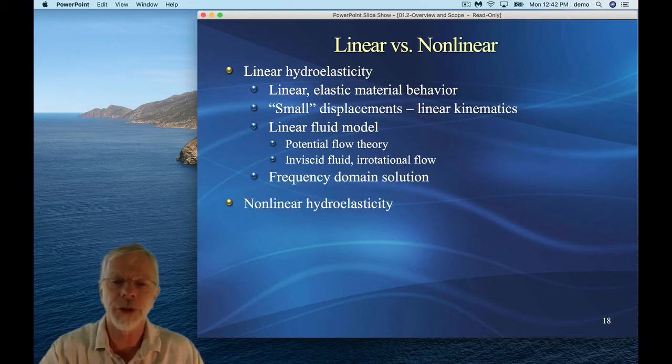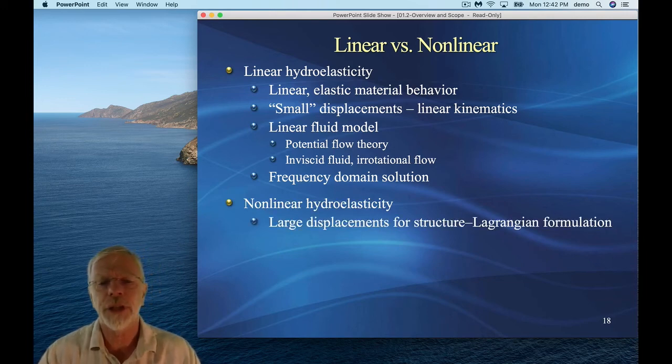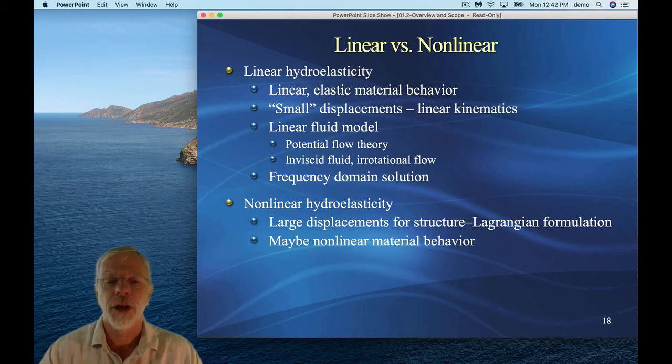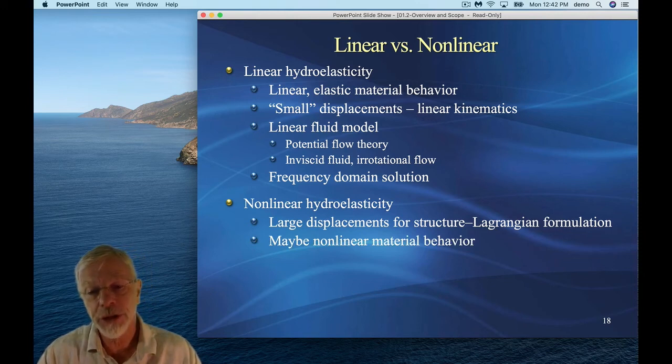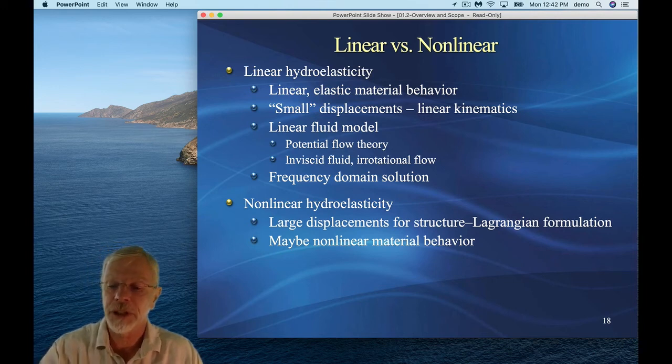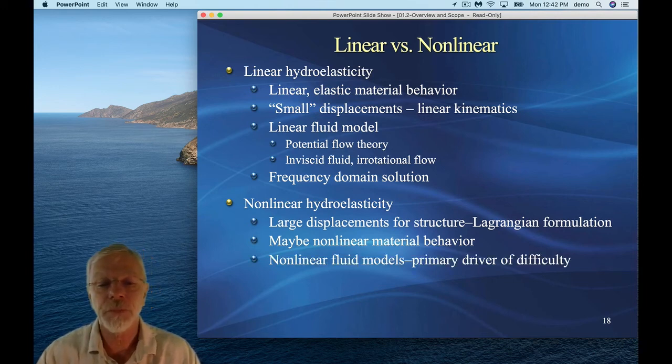In nonlinear hydroelasticity, we can accommodate large displacements for the structure, and we're going to be using a Lagrangian formulation almost invariably for that. We can include material nonlinearity. It doesn't need to be materially nonlinear to be nonlinear hydroelastic. We could have elastic behavior as well.